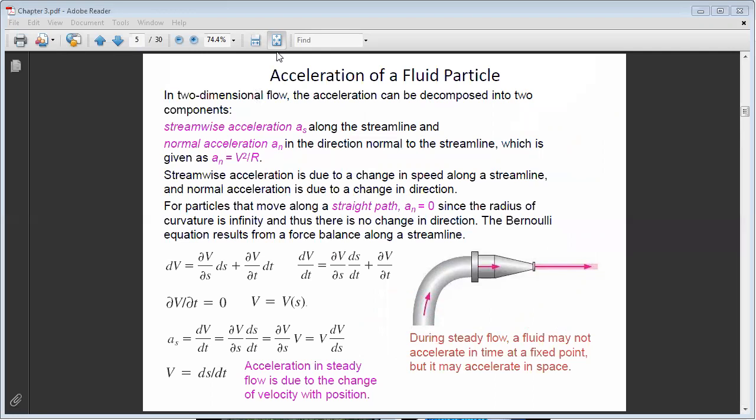If you are concerned, let's say, with the flow within this nozzle, then when I say steady state conditions, this means that I don't have variation of velocity with respect to time at a certain point. So if you are observing the following nozzle here, when I say it's a steady state application, this means that if I look at a particle at the inlet at this location, whatever the time I consider, I will measure the same velocity.